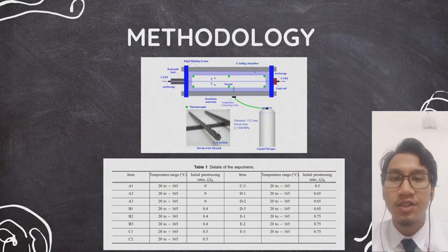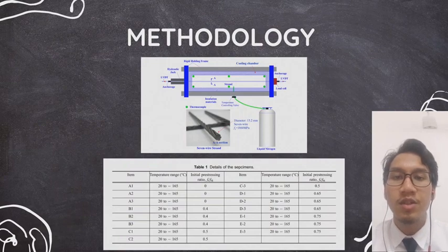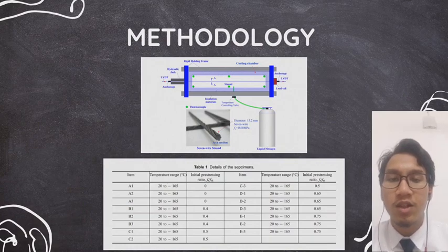During this heating process, linear variable displacement transducers (LVDTs) were used to monitor the displacement at the two ends of the steel strand. All the readings of the sensors, including thermocouples, load cell, and LVDTs, were monitored and recorded by software running on the PC during the testing.